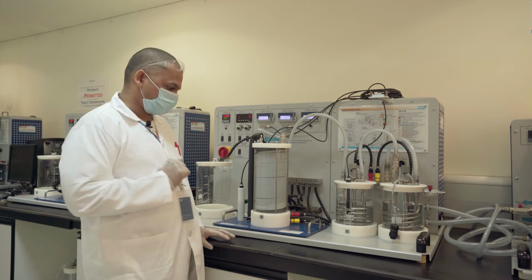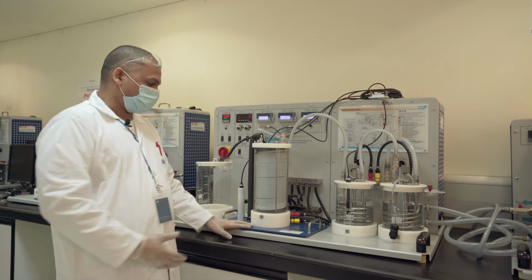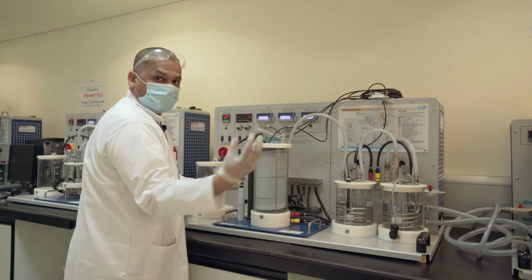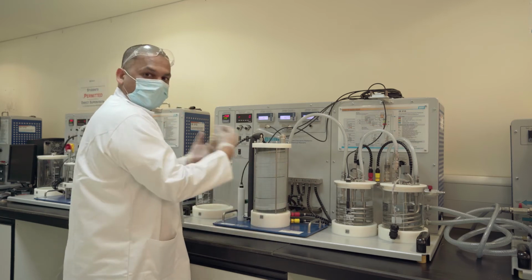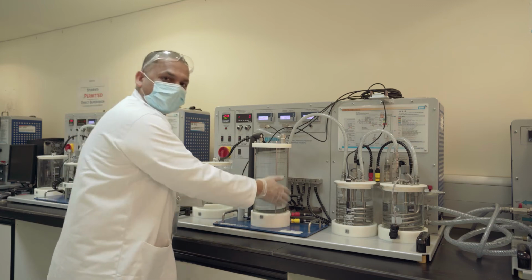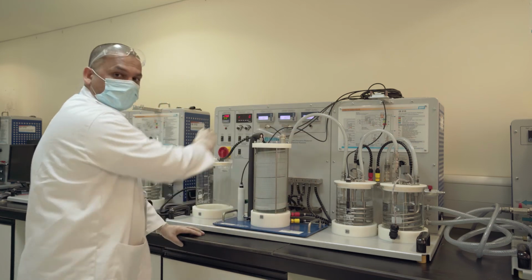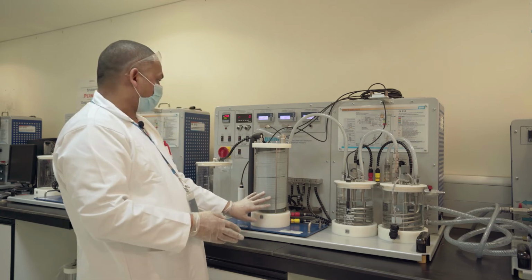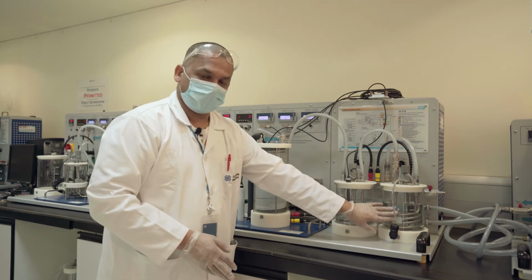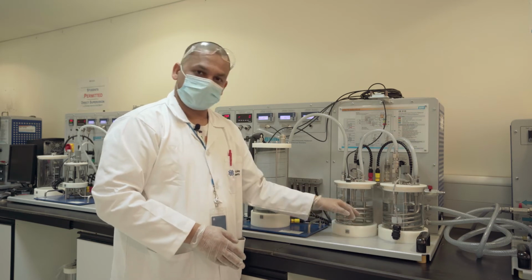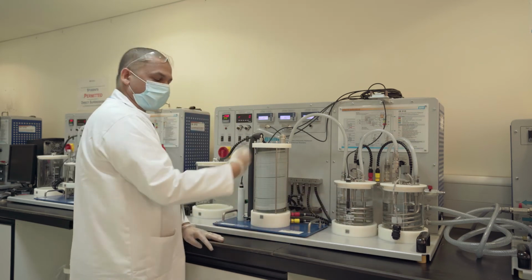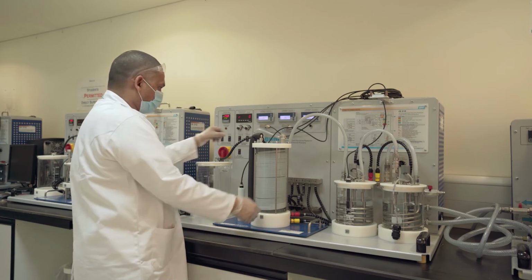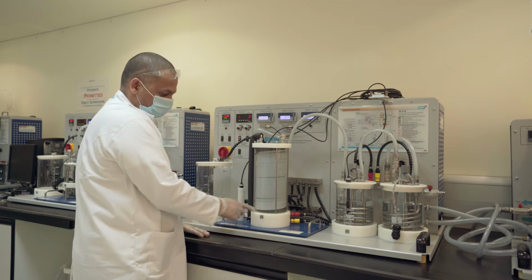I have 2 more reactors. If you see the basic unit, it has just this as an add-on. So I can remove it and put the batch reactor, or I can remove it and put the CSTR reactor. So the same base unit can work for any of the reactors. Okay. So here we take feed A and feed B, equimolar. So the same experiment that you want to do, equimolar first, put it here, and let it pass through the tube.